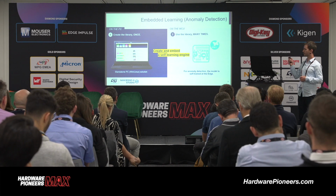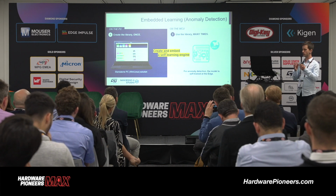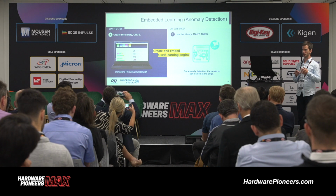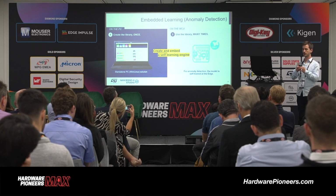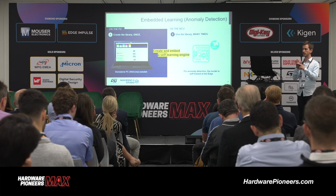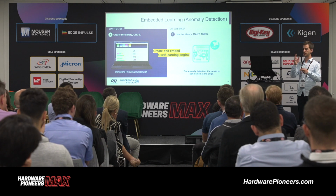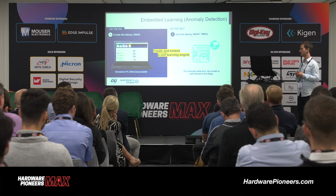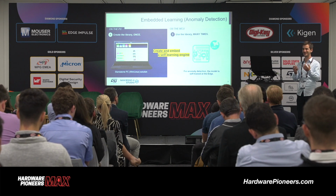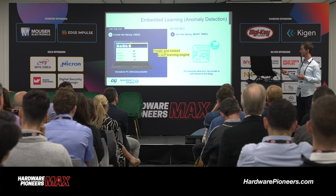Okay, so in order to find these AI libraries, the idea is to use NanoEdge AI Studio. NanoEdge AI Studio is a tool that runs on your PC, and it's like a search engine. You provide it with some input data, then it searches for the best, not only type of machine learning model, but also the hyperparameters, so the shape of this model, and also preprocessing. Preprocessing can be FFT, if you need to look at the frequencies, can be like PCA, if not all your input parameters are important, but just a subset of them, or it can be reframing, standardizing, many different things. All those building blocks will be automatically searched during the process. And then you get the library that you can embed into all your devices.